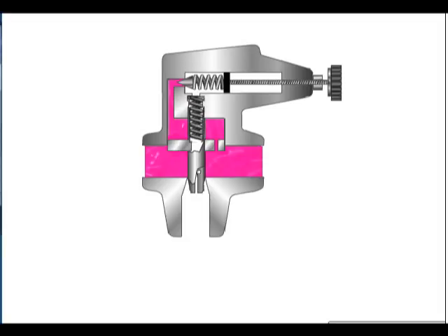When pump line pressure rises higher than the adjustment set on the control knob, the pilot relief poppet moves off its seat. This starts oil flow from the pump line through the orifice, across the pilot relief poppet, and to the tank.